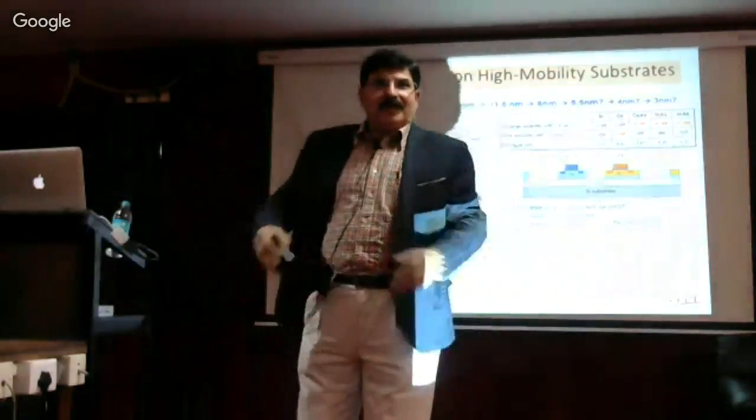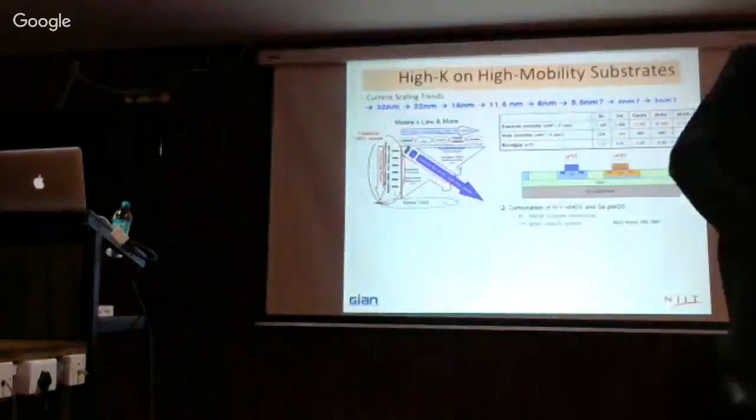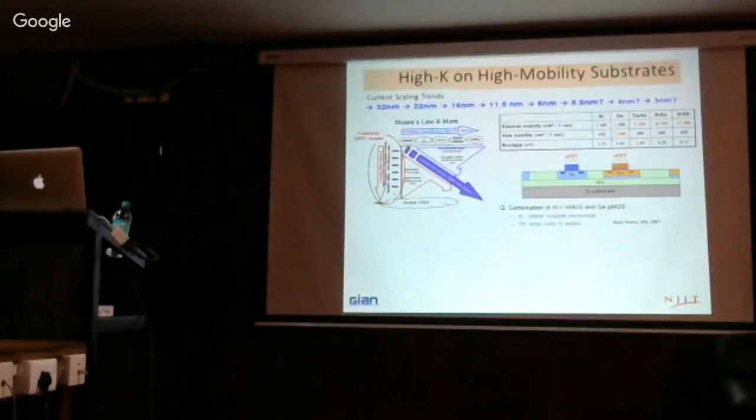No questions. So this interface, that gets leakage currents, is the low frequency noise or high frequency? Low frequency. Yeah. Interface states actually contribute significantly to the low frequency noise. We'll talk about that this afternoon. I put those things together. We had some experiments using FinFETs also. We stressed them to increase the defect density and see how it changes. So we will discuss that.